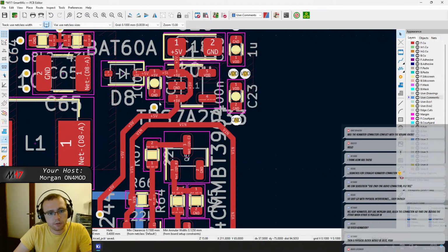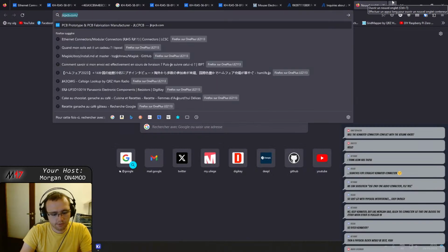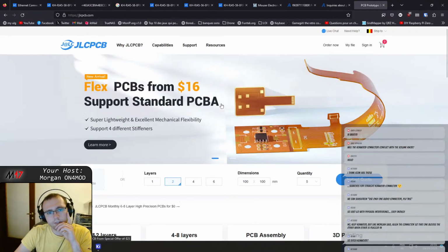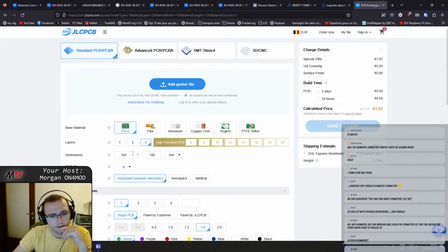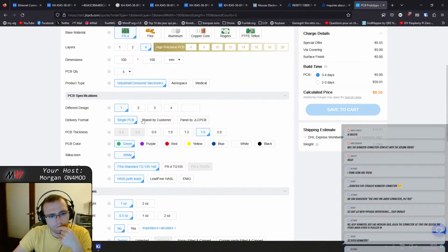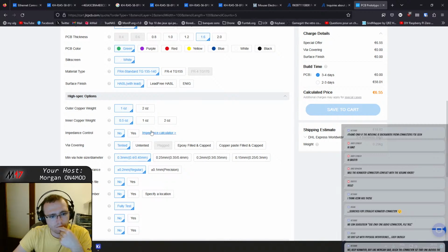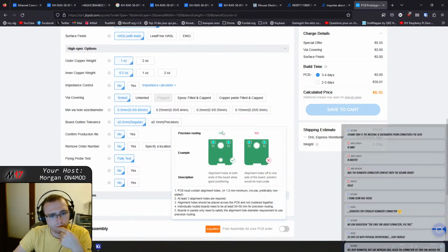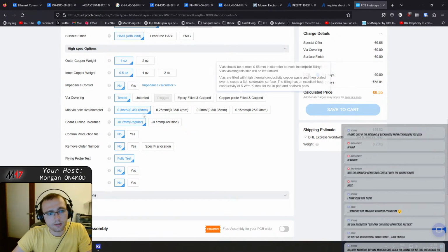No, 0.8/0.4, or no, wait, what? 0.6/0.3. Let me just have a look at what is standard from JLCPCB. Wait, 0.6/0.3 is enough. Great.